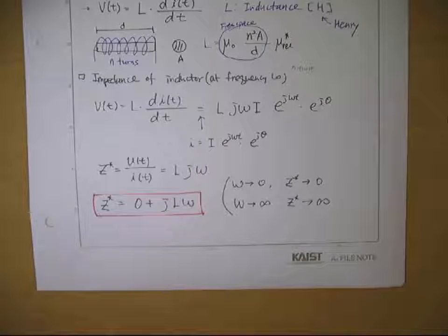So that makes sense because you have a coil, but when you apply only DC current, the charge will just flow straight through the inductor. But as soon as you apply an alternating current, there will be some accelerated charges moving, so that you have a magnetic field created too. Then the impedance will increase.